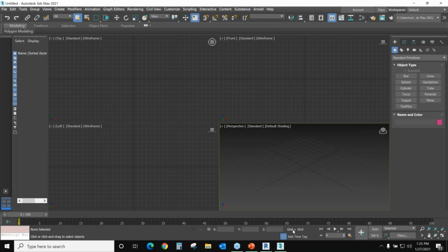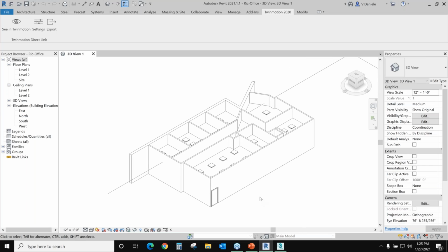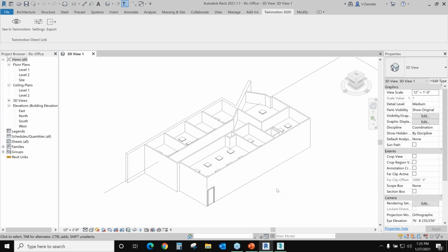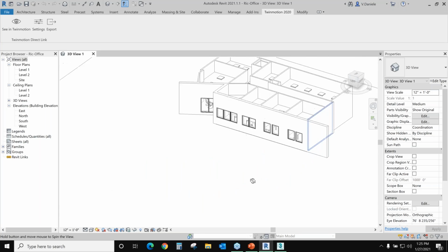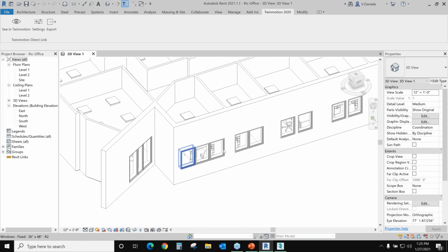So, taking a step back, what Jay was talking about with CloudWorks for Revit, the plugin that allows us to actually model off of the scan. We've got this example, our Richmond office in Richmond, Virginia, that Jay and one of our other guys, Jeff, scanned using a Leica scanner and processed the point cloud. Then, using that workflow Jay was talking about, we were able to produce the 3D model, extremely accurate based off of the points, with windows and everything.